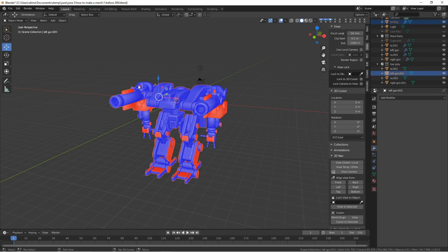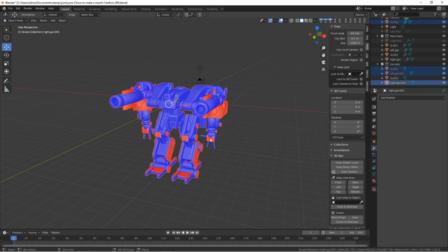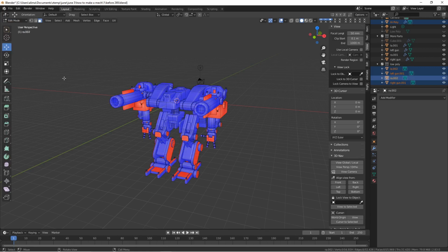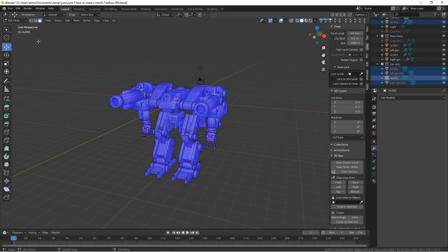We'll hold shift and select all of the places where we see issues. So I'm letting go of shift. So I selected all of those objects. Now I can go to the upper left. I can go into edit mode of all of these objects at the same time. I'll press A. Then I'll hold shift and press N. So I've recalculated all of those normals all at the same time. So I'll left click to deselect, go to the upper left, and then go to object mode.